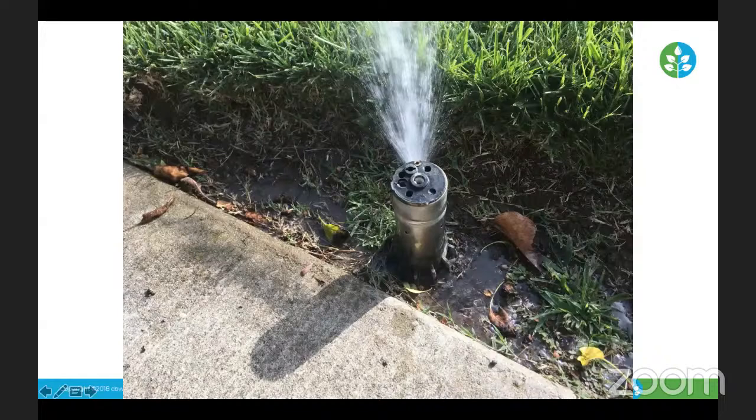So is there a problem here with this irrigation valve? There are a couple. The top part of this rotor is damaged. That happens. This is in a park area, but in any high traffic area, people step on it, or when they take the weed eater to clean this area out, they could damage it. It seems to be working all right, but the issue here is that the grass has grown much higher than the soil level over time. So now all this runoff here is a deflection of the grass surrounding that sprinkler.